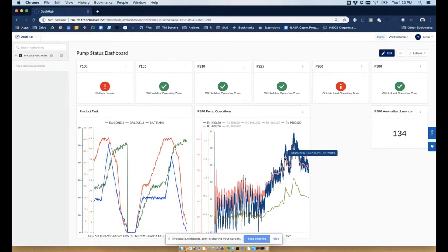And essentially what I want to look at, one of the main indicators of pump health here is how well we're operating the discharge filter. So we know from past experience that if the pump runs too long with the foul discharge filter, then we end up having issues with the pump and we have to shut it down and do mechanical repair.